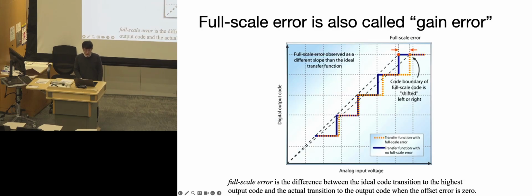And to that, we also have the gain error. You can think of it as a slope change. It's when the actual output or input, depending on whether you're talking about ADCs or DACs, diverges from the expected value proportionally across all the input and output values. So essentially, the slope is going up or down a little bit. If you think of each of these value points as the points you connect together for the slope, you could choose the middle point or the edge point. It doesn't really matter as long as you keep them consistent.